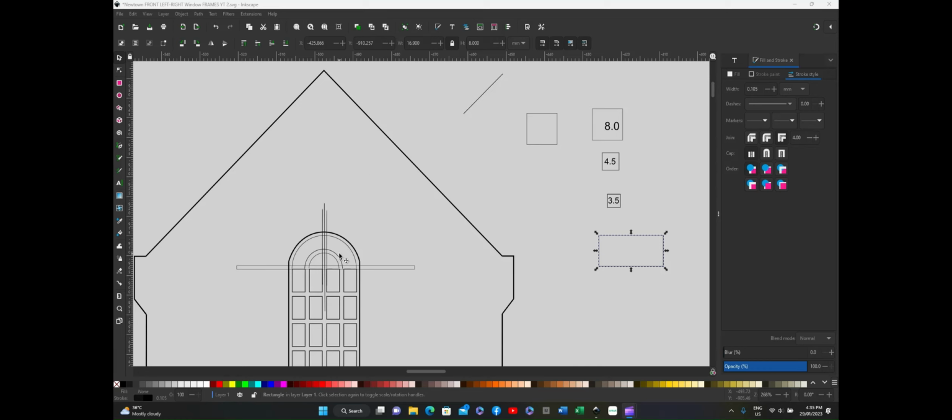The next is to find the center of this arc. The way to do that was I made a box, square, which can rest in here, right to the center. Now center to center was 8, as you can see. So what I did from there, I then drew a line directly from that corner out over, which then gave me the center that I require. I can now take the box away, and we are left with the indicator for where the center is.